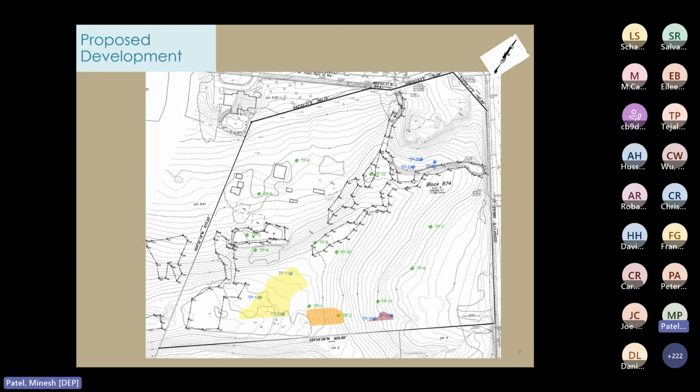Your review would also include a check of whether a sufficient number of test pits and soil borings were performed, along with the depth of the investigation, which I'm not going to cover here because we're focusing strictly on GI right now. But I've also added the depth at which the logs show the soil permeability was determined, taking note that groundwater was not encountered at any of these locations.